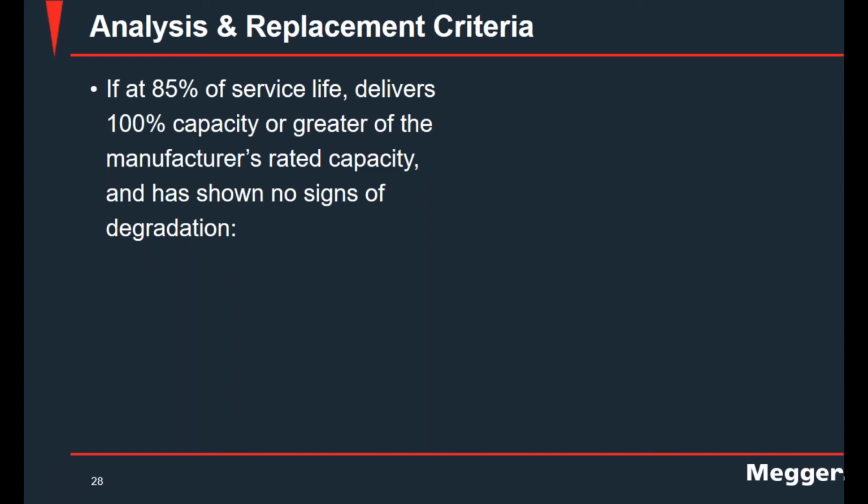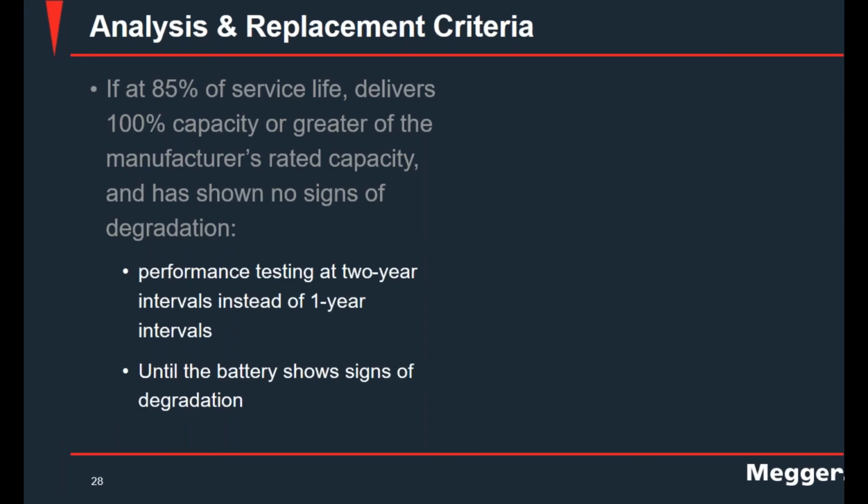You just test every 2 years until the battery shows signs of degradation, and that degradation is defined as a capacity drop of 10% from a previous test.